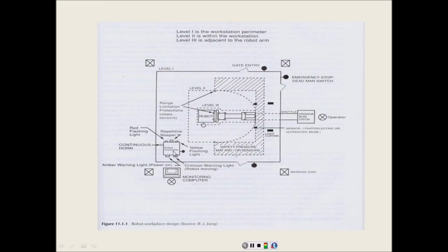So it's got to be out far enough so no matter what happens, the robot can't hit the controller, which should make sense. Because the controller is the computer that's running the robot, and if the robot hits it, you could cause squirrely things to happen, right? So the controller has to be outside of the reach of the robot, which would be the maximum space, right?